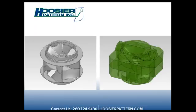So the print envelope that we have is say 71 inches by 39 by 27 and a half. And a lot of people do castings larger than that or need molds larger than that. We've been asked many a time, can you do larger items? Absolutely you can. To do this particular impeller, it was going to take 4 different prints and we'd piece the cores together. We've done other projects where the core is 100 inches long and it's literally bolted together. So you can go large. It's like playing with Lincoln Logs or Legos from when you were a kid, or maybe you do it with kids now. But you can go large as you need.